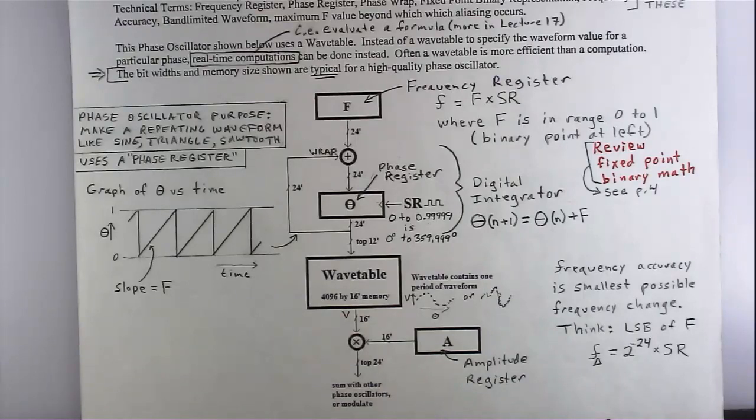But let's say you had the example I had before. Say you're in the lab and you're playing your sine wave generator, and let's say you're running at 44.1 kilohertz sample rate, same as CDs are. A lot of stuff is recorded at that rate still. And let's say we play a 1,000 hertz sine wave. How many samples are you getting per period? About? 44.1 kilohertz and a 1,000 hertz sine wave.